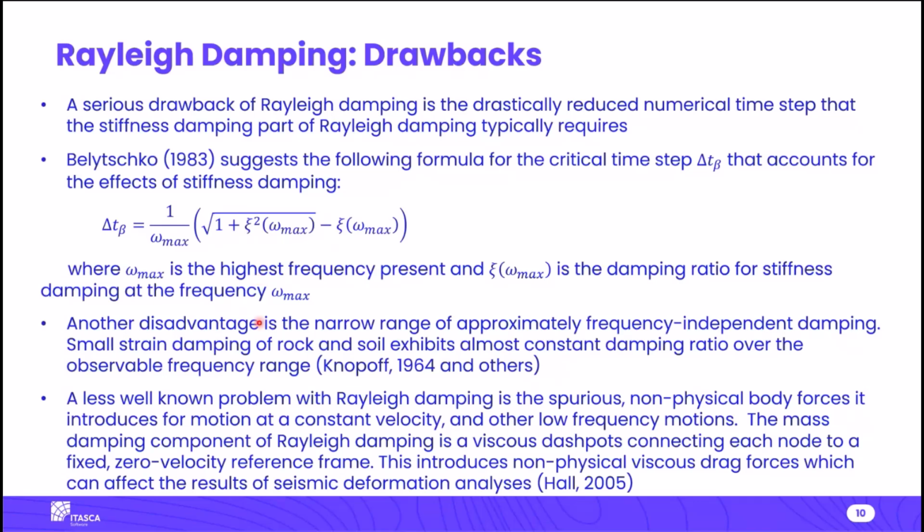Another disadvantage of Rayleigh damping is this very narrow frequency range of frequency-independent damping. Ideally you would have constant damping for all frequencies, because it's been shown that the small strain damping of rock and soil exhibits an almost constant damping ratio over the full observable frequency range.